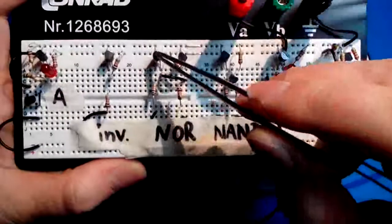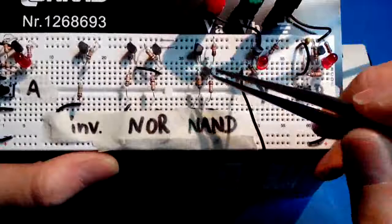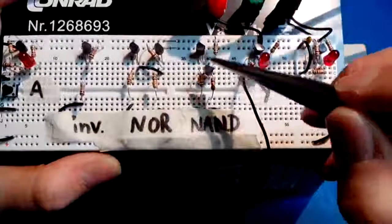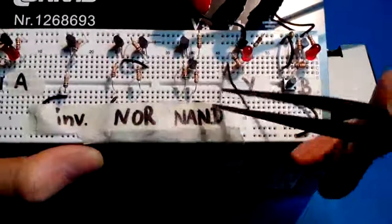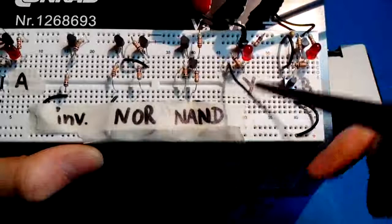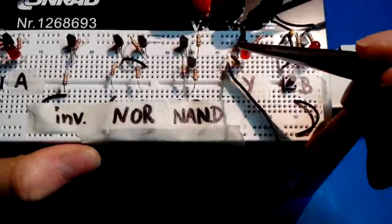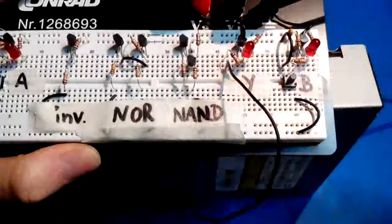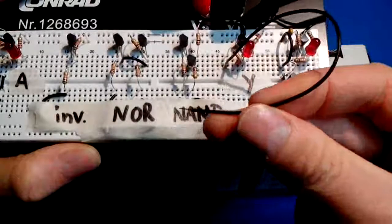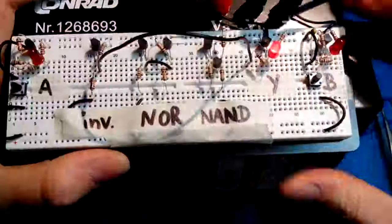The NOR gate, as you saw, has 2 transistors and 3 resistors. A NAND gate also has 2 transistors in a slightly different configuration and 3 resistors. Now we have one Y, that was the output. There's an LED indicating the output. The output is basically this wire. We can stick it at the output of each of these gates to see what happens. Let's first stick it at the output of the inverter.